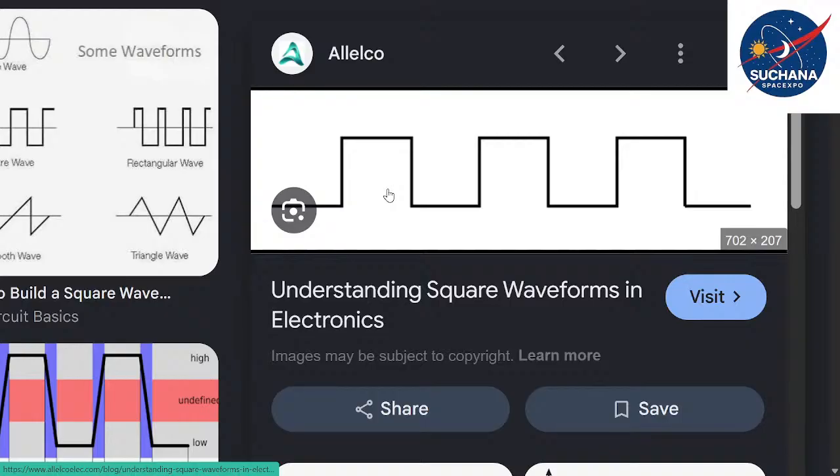Okay, so the operating voltages vary from board to board. For ESP32, it's 3.3 volt, whereas for the Arduino UNO module, it is around 5 volt. Okay, so there are two different kinds of signals that an Arduino UNO can accept or generate. The first is the digital signal. A digital signal is discrete, meaning with respect to time, it can have a value of either 0 or 1. Okay, 0 means low, 1 means high.